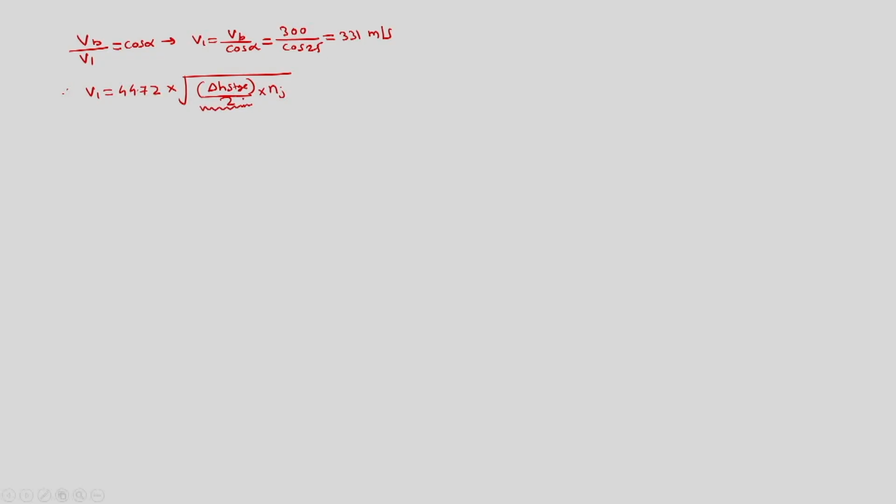Here we are dividing by 2 since half of the enthalpy drop of the stage takes place in the nozzle, which gives us the V1 velocity, and half takes place in the moving blades. So what was the complete delta H in the case of impulse now becomes delta H by 2 for the 50% reaction, and this is equal to 331.